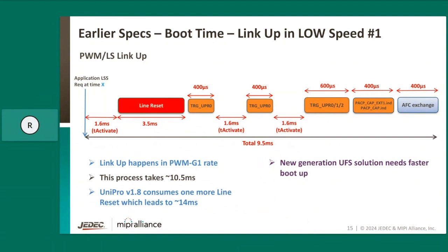As I said, one of the areas that UniPro 2.0 is addressing is to reduce or optimize the boot time. Before we understand where it introduced the optimization, let us have a look at today's solution, or the so-far solution, in UFS for boot-up operation. Boot-up used to happen in low speed, which is nothing but the PWM link-up process.